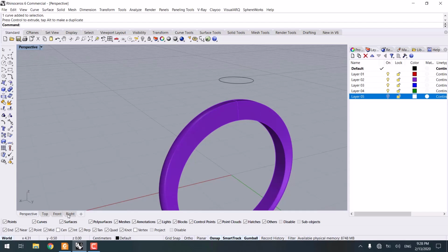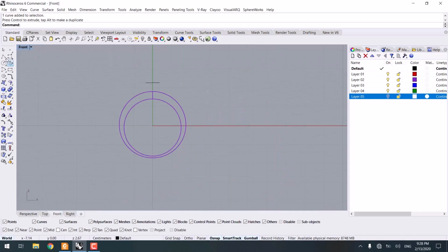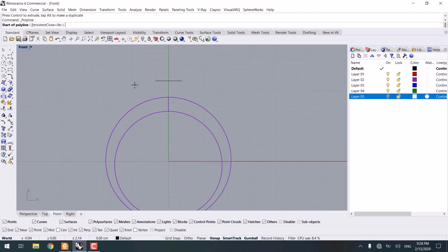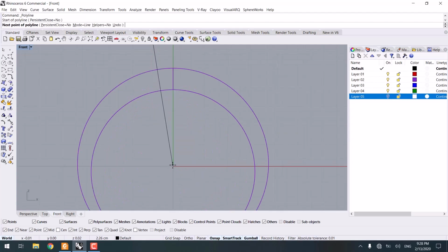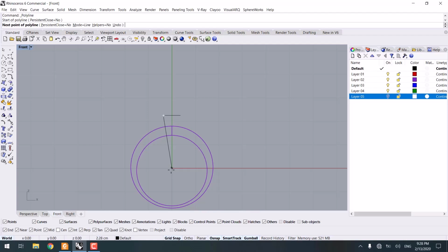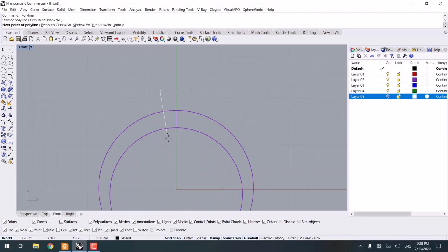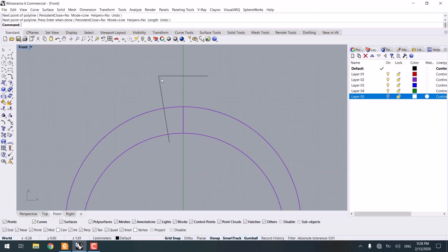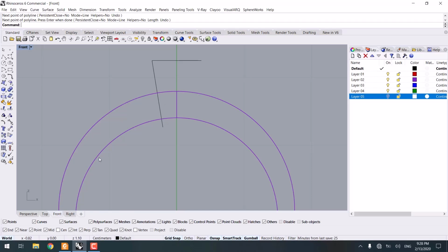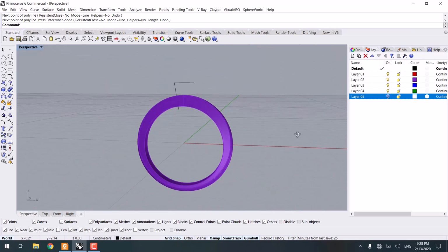Now, as my next step, I'm going to go ahead and select a line and try setting a line or actually connecting this quad to the center point of this circle using grid snap. And also I need to press tab on the keyboard, and as a result I would have a line here like this, and it'll be locked down.